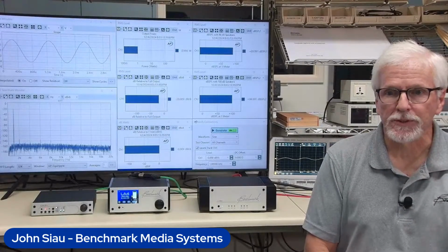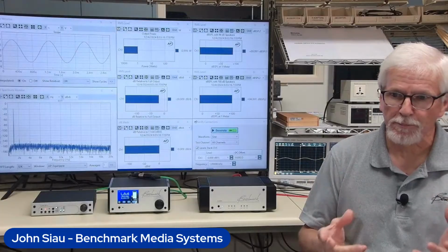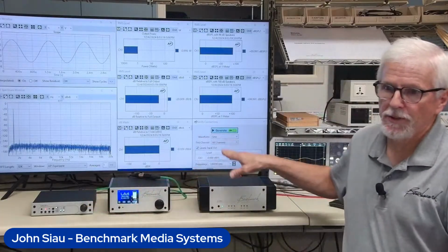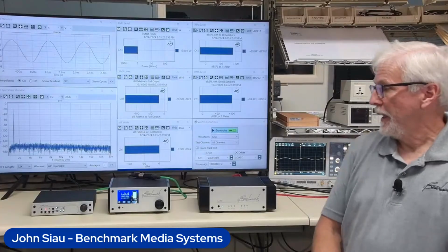So that's what this topic is about. It's about achieving proper gain staging between each of our devices in our system. Would you agree with me that you want to do most of your voltage gain at the preamp level, not at the amplifier level? You want to take your gain as early in the system as possible. So the sooner I go to a high level signal, the better I am going through the system. I'll have the best signal to noise ratio when I boost the signal in the beginning and take as little gain as possible in the power amplifier.